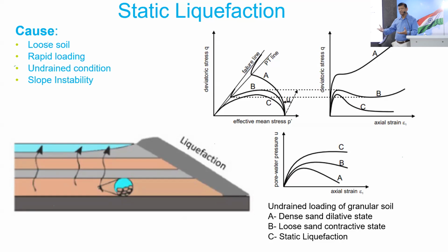They also did some stability modeling, limit equilibrium based stability modeling, and they designed it for 100 feet more dump on top of the tailings. Initially they put 50 feet, all over the tailings, but when they went and put the next 50 feet, it failed.